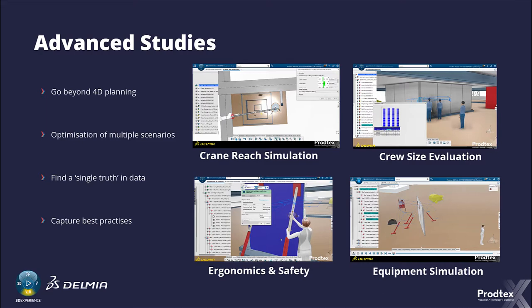So just on that note, as an example, it could be that you're looking at things which are happening maybe hundreds or thousands of times on site, such as pouring a concrete column. To do that, you need to place the rebar, set the formwork, pour the concrete, vibrate the concrete, let the concrete cure, strip the formwork, and that needs to be done for every single column on the project. So those are the kind of highly repetitive activities which you may want to optimize on the site.